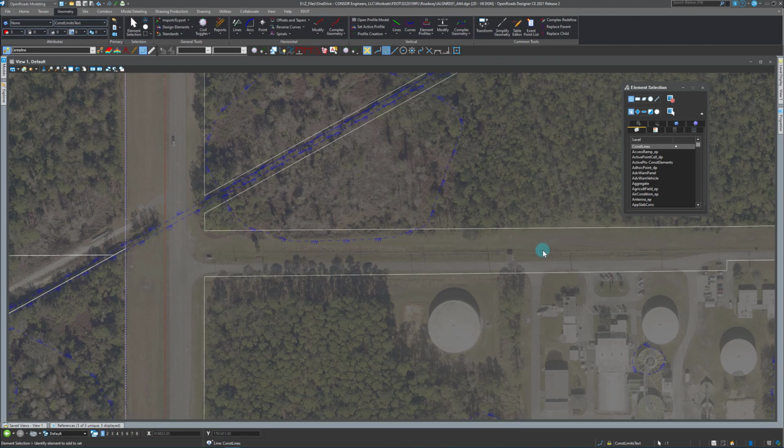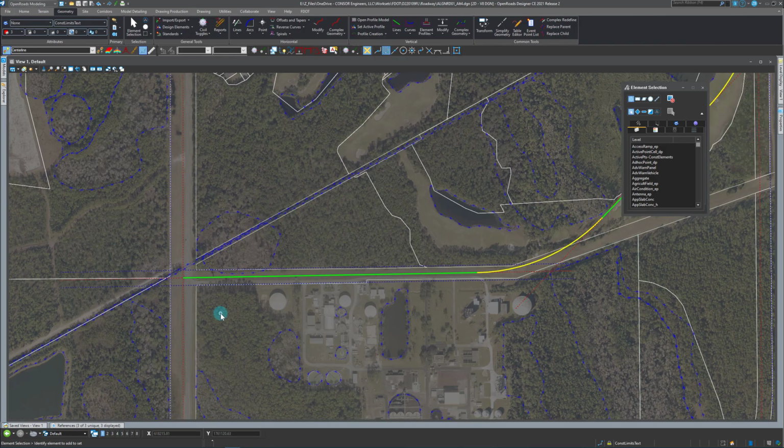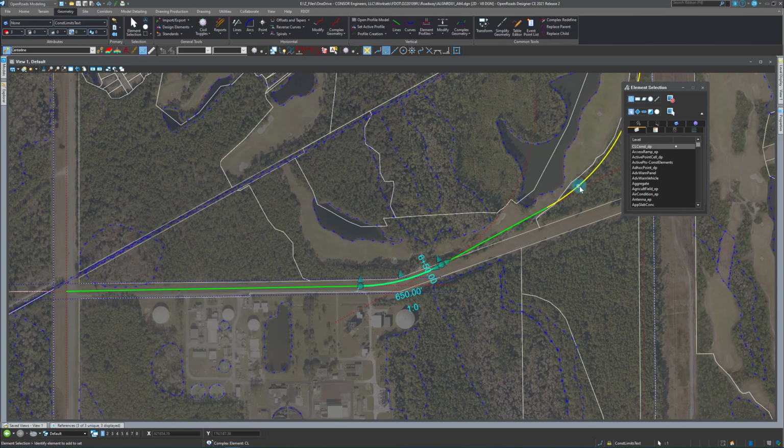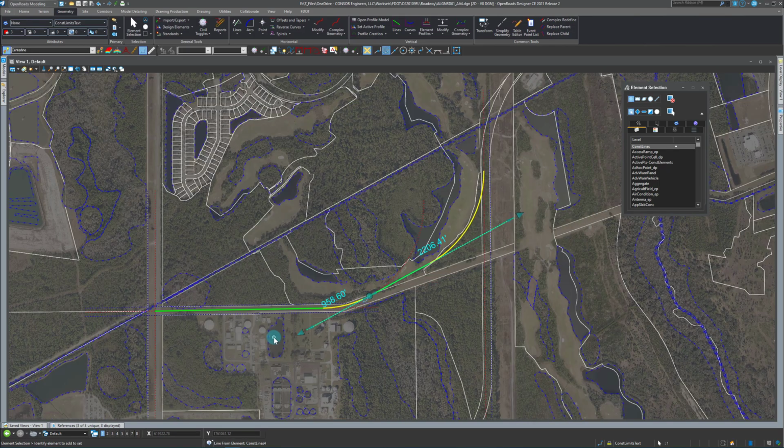I broke it. Didn't like that. I have to do 0, 0, 0. So I change that, I've got the bearing changed, where I want to reduce this distance to 650 feet. Now we're changing that distance there. Starting to play with that.